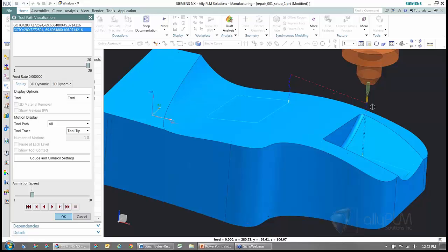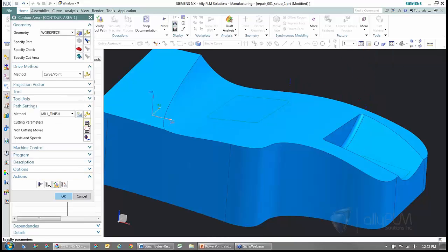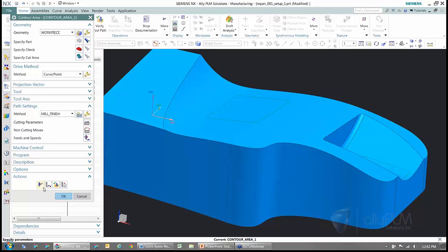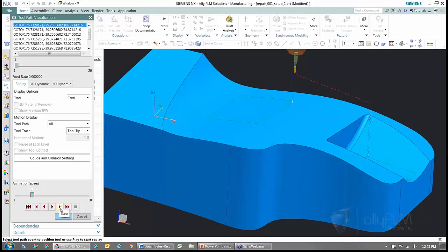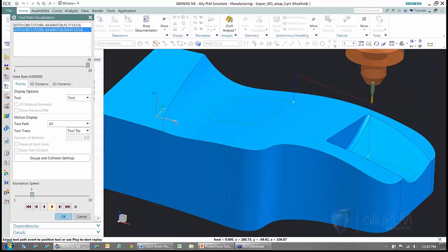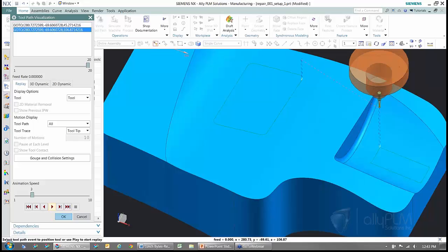So now we've basically driven our toolpath according to the outer lines of the two design changes. And I can apply a negative stock amount so that this will actually engrave the part slightly. So again, we will engrave these outlined areas so that the welding department knows the size, shape, and location of the two design changes.